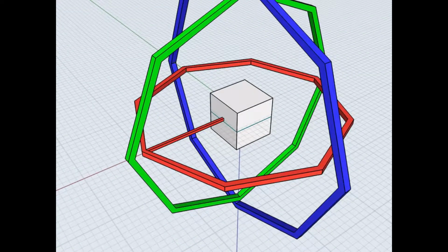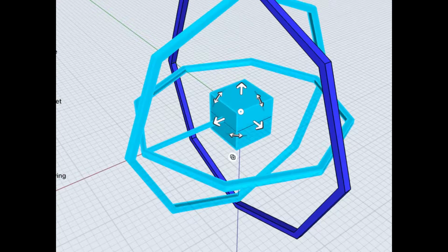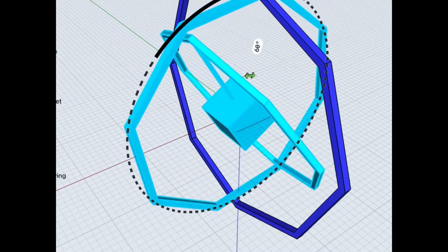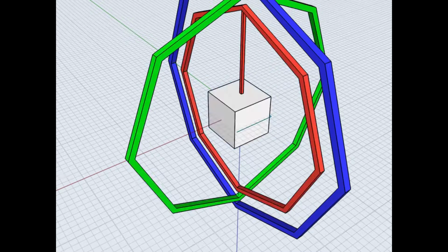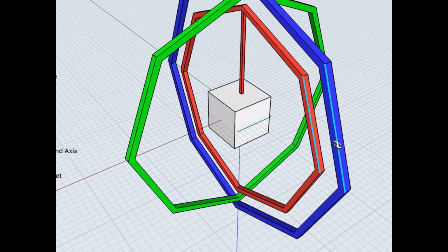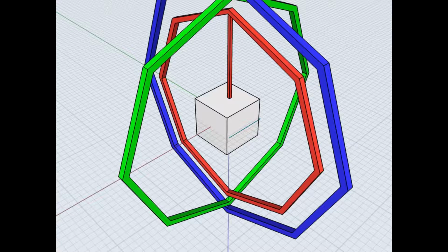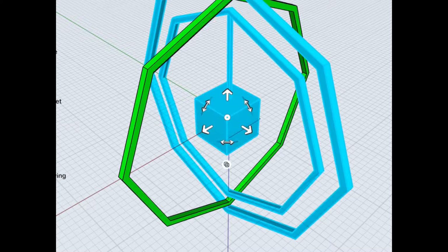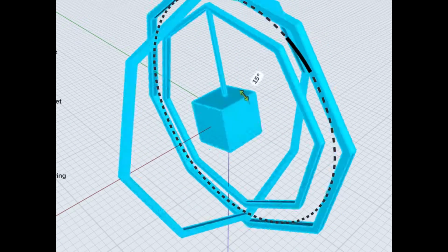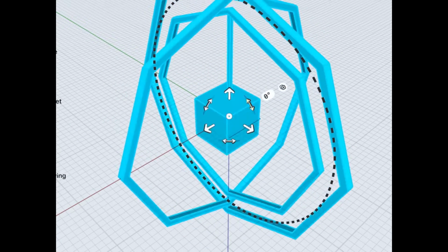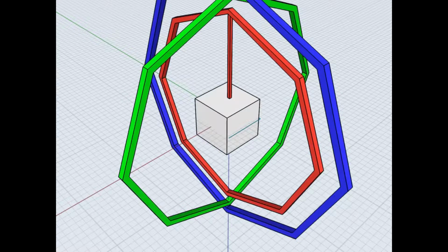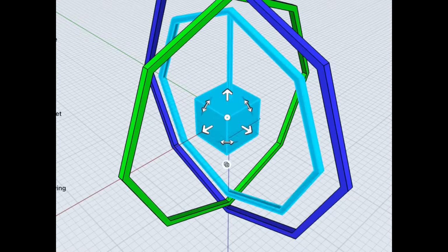Using this system, if we have a 90-degree pitch change, you can see that the X ring is now aligned with the Z ring. In this configuration, there's no way for the cube to tell the difference between a change in the blue Z ring and the X ring.